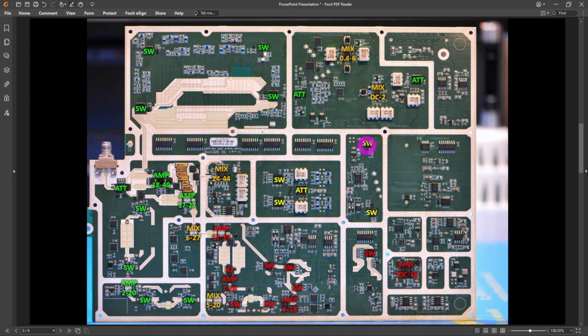So here's the PCB. Now I went ahead and put some labels on some of the components that are critical, and I wanted to talk a little bit about how they've put it together and what are the ways that you can actually quickly understand the architecture of something as complex as this without really digging into the details. So I put just some of the crucial ones. All the green labels are the RF paths, and all the red labels are what I think are on the yellow path. And there's a couple of yellow ones which are the IF, and the mixers are in orange. As we said, there should be about 5 mixers at least, and we can see that there is a mixer covering 24 to 44 gigahertz.